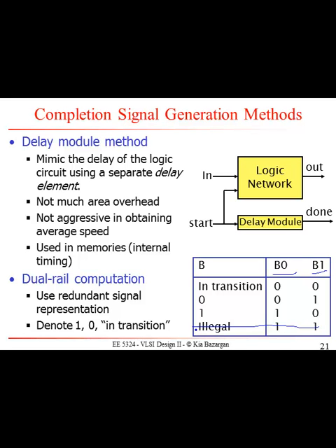It's similar to doing pre-charge logic. If you pull down the output, you know that the computation is done. Except that in the regular pre-charge logic, if the signal remains at 1, you don't know if it is the pre-charge value that is remaining the same, or if the evaluation was done and decided to keep the pre-charge value.